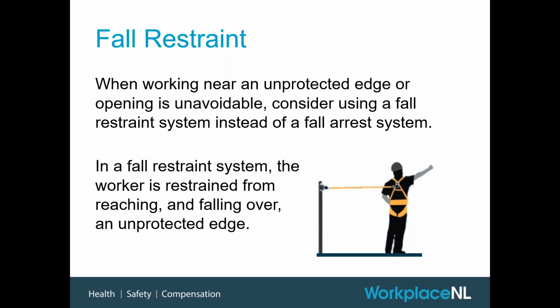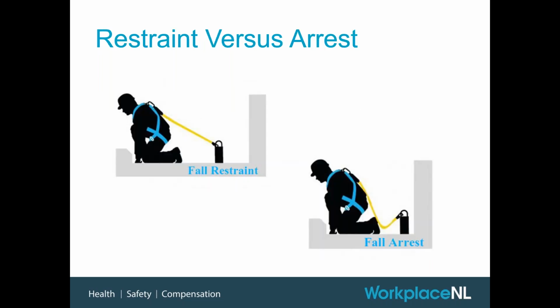So there's, again, planning involved here as far as setting these up, and it's important that the right pieces of equipment are used that don't have extra give that can make the line longer. So we think about stuff like self-retracting lanyards. They wouldn't be used in this particular scenario unless you base it on the fully extended length of that SRL.